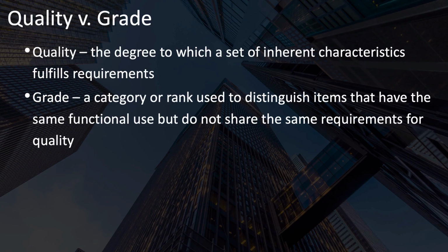Consider the example of a house that has different electrical circuits for different rooms and areas of the house. Each of these circuits is routed through a panel of circuit breakers of various amperage. If you put a 50 amp circuit breaker on a circuit that's rated at 20 amps, you've installed a higher grade part, but created a fire hazard because the circuit breaker won't trip and stop the flow of electricity when the circuit is overloaded, and this can start a fire.